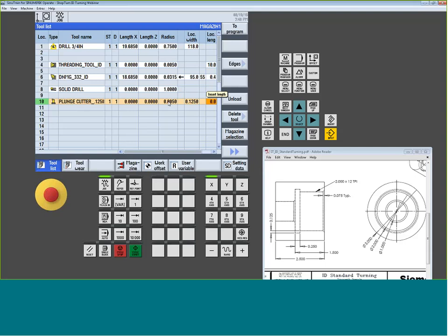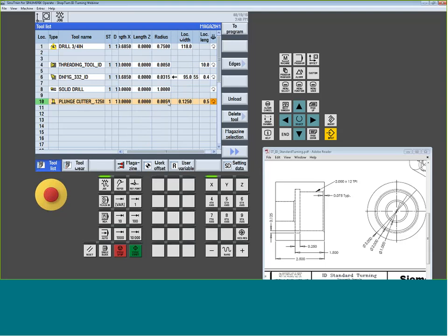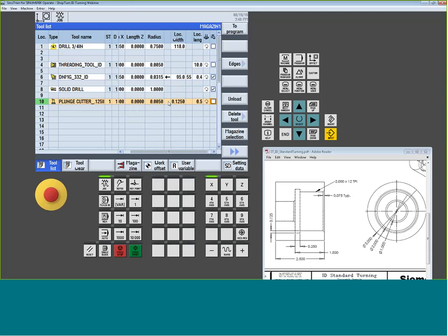The length of the insert is just for the picture. If I give it a length and it's grooving deeper than the length, it'll let it go. It's just the insert length. The holders themselves can project those inserts way out. Then certainly everything else would normally stay the same.